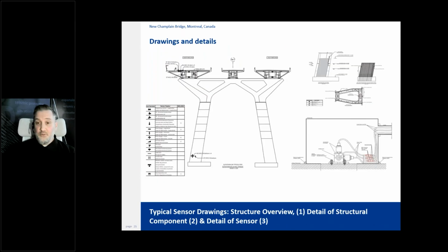This new bridge is 2.1 miles long. It includes a cable stayed structure that you could see in that previous picture maybe, with a main span of 240 meters. The superstructure, as we see on the left side of this selection of drawings here, is designed as 3 independent parallel structures, so those structures you see at the top. The outside two are 3-lane vehicular traffic corridors, and the center is a rail transit corridor that has 2 lanes.